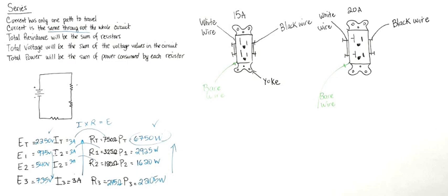Because how easy is it for you to get behind your range to put an extension? It's not easy. And it's not safe because you have heat behind that range. And putting an extension cord and running it somewhere else is not safe. So if the customer does that, and you see it, advise them not to do it. But that's why we put just one receptacle behind the range. And that's just something that we do because we don't want the customer to have another receptacle where they can plug into something else, because they don't really understand how dangerous that can become. But those types of receptacles, you have to have a dedicated circuit.